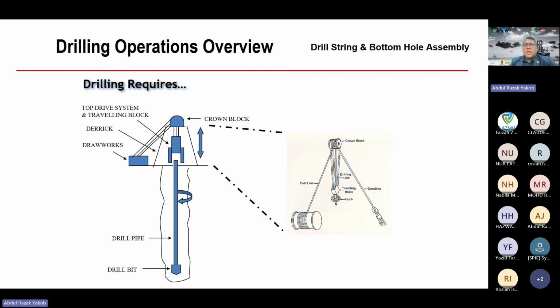Just imagine the drill pipe is about 9 meters each. Usually we will put it in a string and run it in hole. We put together 3 joints, that means about 30 meters. The three joints make one stand, and we bring down one stand in the drilling process. So every time, one stand, one stand, one stand, we need to first make up the 3 joints into one stand. All of this is the drill pipe that is brought down, one joint going down after another.